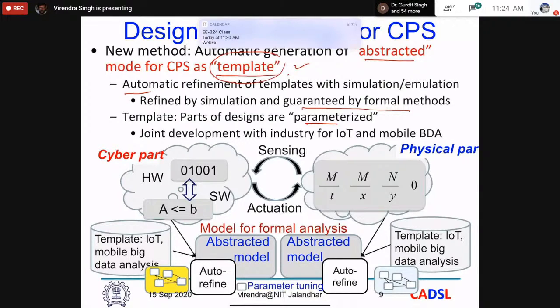When I partition my design, there are many internal signals crossing from one part to another, and your FPGA may not support that many input outputs. If it cannot support that many input outputs, you need to further divide the design, and therefore you may end up with a large number of FPGAs to build your significantly complex design.